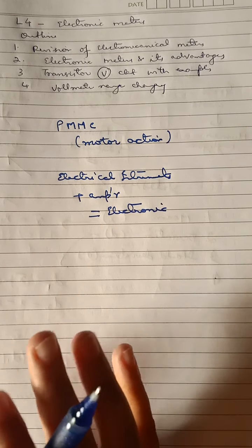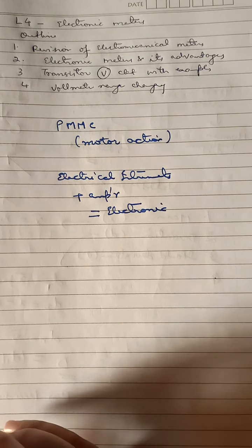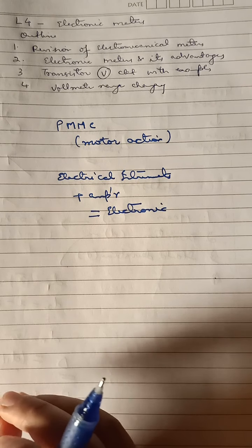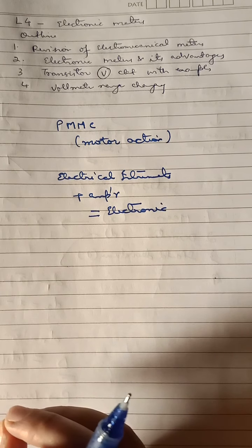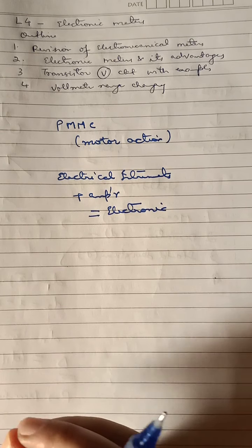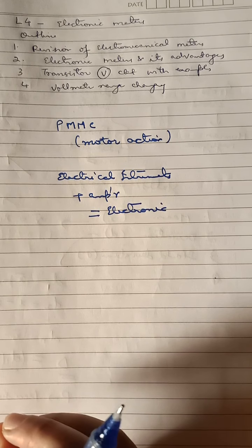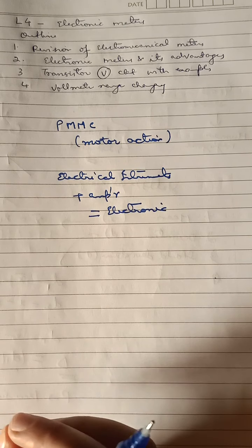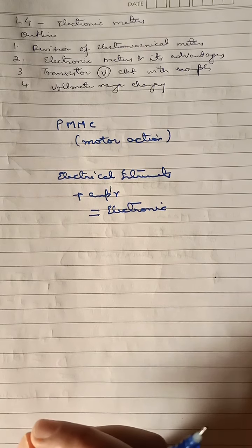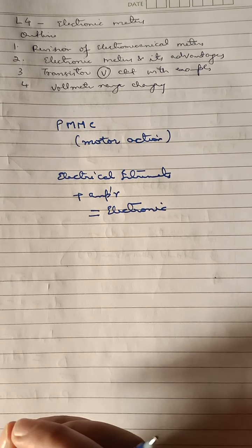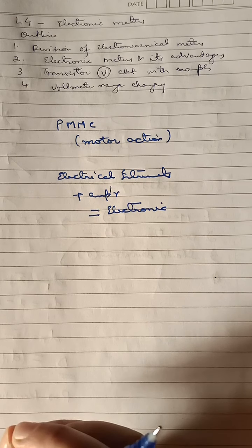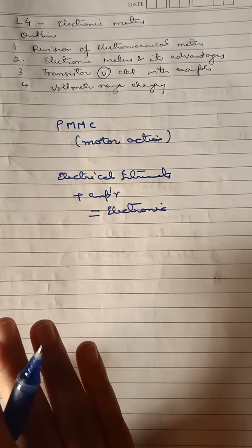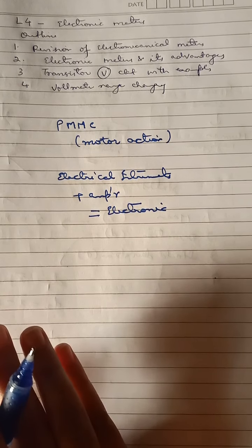Let us talk about an electrical voltmeter. There may be certain voltages which are very small. Since any electromechanical meter works on the motion of certain parts of the instrument, when the voltage is so small that it produces such a feeble current and such a feeble magnetic field, the pointer is hardly able to move or show you the correct reading of that particular quantity. So in that case, its sensitivity is less. Basically the sensitivity of electrical instruments is far less.